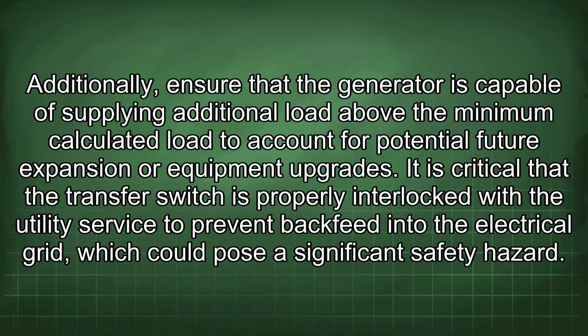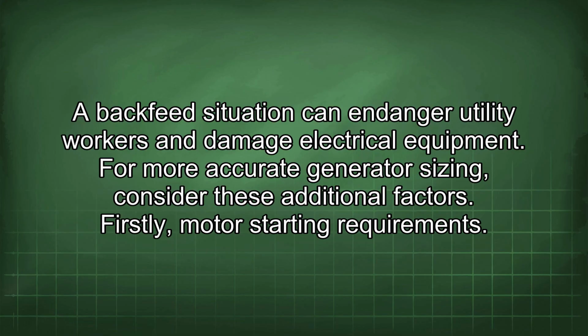It is critical that the transfer switch is properly interlocked with the utility service to prevent backfeed into the electrical grid, which could pose a significant safety hazard. A backfeed situation can endanger utility workers and damage electrical equipment. For more accurate generator sizing, consider these additional factors.